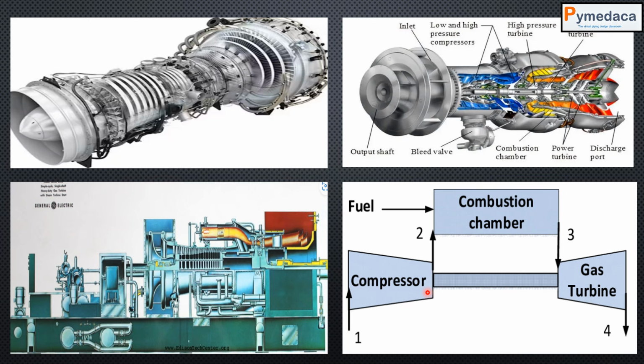But the one most important thing you have to understand is that compressors and turbines are equipments that are purely manufactured by the vendors. So the size of the compressor from one vendor to another varies, and most importantly the configuration also varies. You will not end up having a typical compressor of the same size or the same nozzle orientations and everything. Based on the different vendors you will have a different configuration. So what you have to do is just change your piping accordingly in order to meet the requirements.